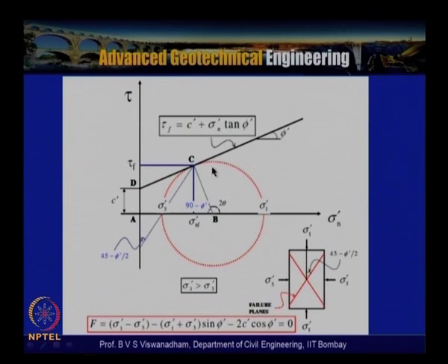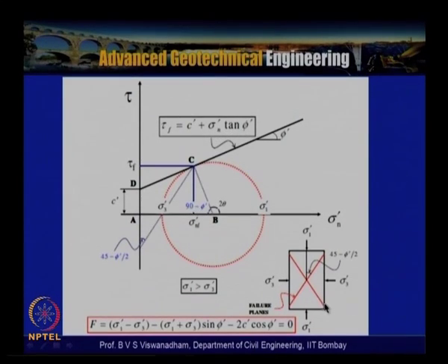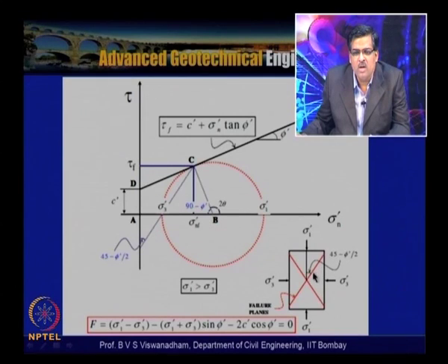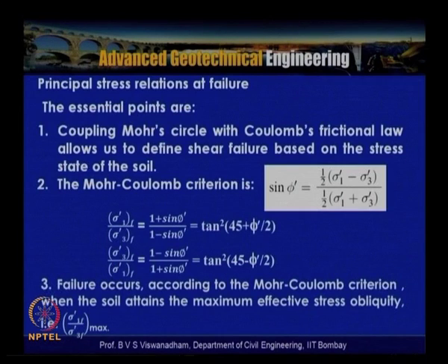So, here further this is indicated, wherein we have the failure plane which is inclined, with the conjugate failure planes also shown here. This is the conjugate failure plane, and when the sample is homogeneous, as has been told, this is possible. And so you have failure planes which can have inclinations 45 plus phi by 2 and 45 minus phi by 2.